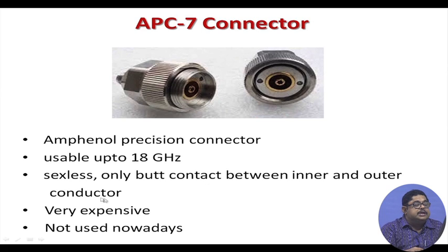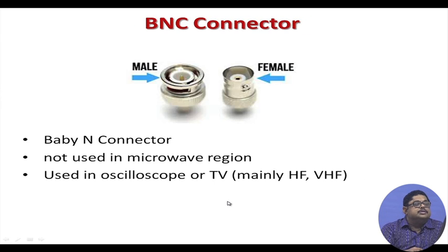Then APC, the name comes from Amphenol precision connector. This is the only connector which is sexless, only butt contact between outer and inner conductor. So, good, but it is very expensive, not used nowadays. If you buy any very expensive thing, like recently we bought one expensive network analyzer, there it was given APC, but otherwise nowadays most of the things are SMA connectors.